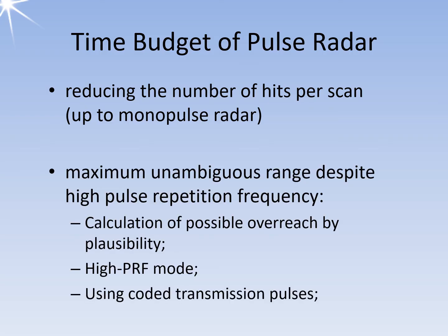With a different internal modulation of the transmit pulses, echo signals can be assigned to the corresponding transmit pulse. This means that a runtime greater than the pulse period can also be detected. With multi-function radars, even different tasks can take place simultaneously. For example, a strongly focused pattern can be transmitted to track a ballistic missile, and while waiting for the echo signal, other pulses can be transmitted for surface search.